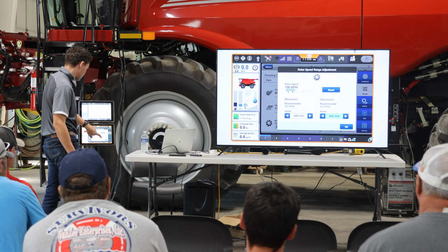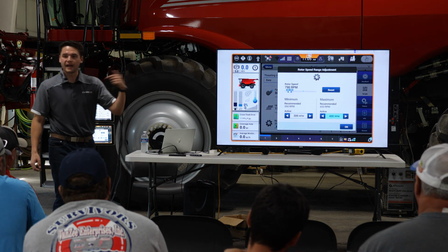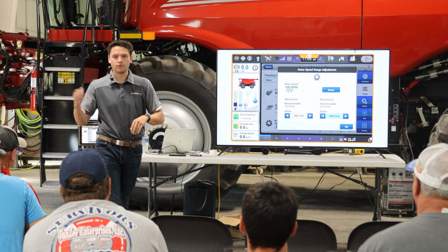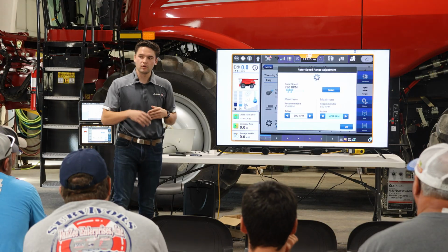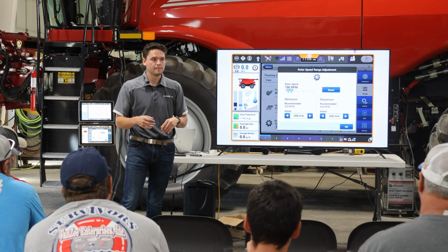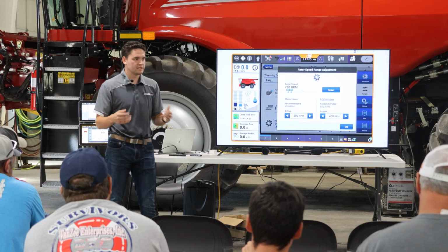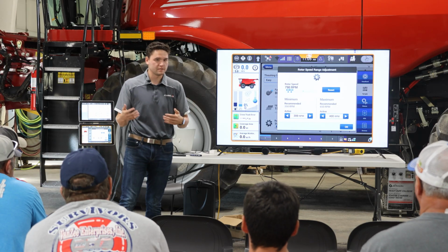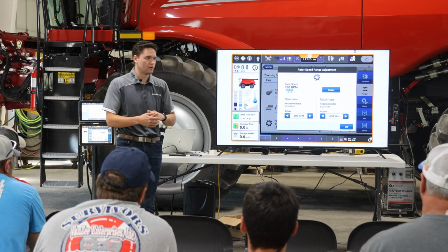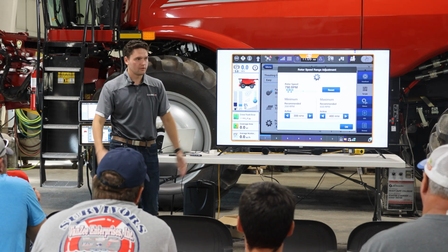Tell the machine, hey, when you're learning our settings and what setting works well to produce the outcome that I want, when you're doing those tests of anywhere from 300 to 450, you're no longer able to do that last 50 RPM. You can only test between 300 and 400 now. So when it tries to get its max productivity, its highest level of rotor speed to get that productivity is now 400. So it won't go into that last 50 RPM that you always saw producing broken grain outputs. So again, it's like producing guardrails.